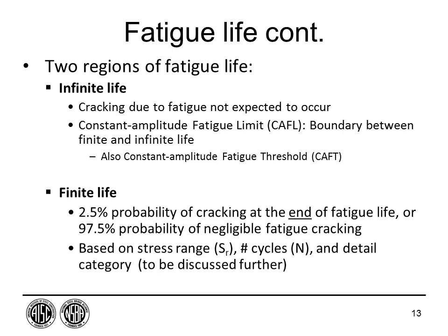So if I go back to the paperclip illustration, and you bend the paperclip just a little bit, millions of times you might find that it never cracks. And that's what we're talking about here: it has infinite life, an infinite number of cycles at that stress range. That's referred to as the constant amplitude fatigue limit, or the constant amplitude fatigue threshold. The other region, though, that we generally worry more about is the finite life. This is the portion of the life curve where, yes, cracking could be expected.